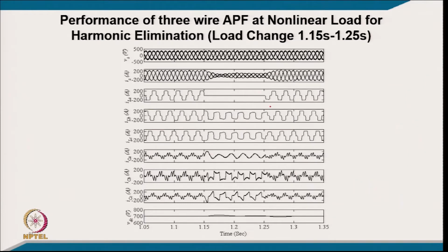So, of course, in this phase now you have a sinusoidal current, but the other two phases will be the difference of this sine wave and this wave, and you will find that the supply currents are balanced, sinusoidal and at unity power factor. And there is a DC link voltage regulator, otherwise you cannot have operation of a D-STATCOM.